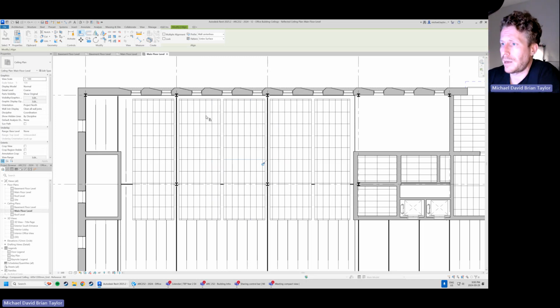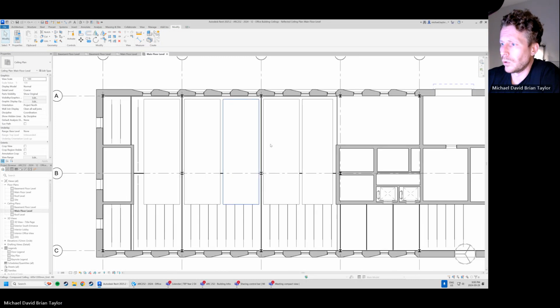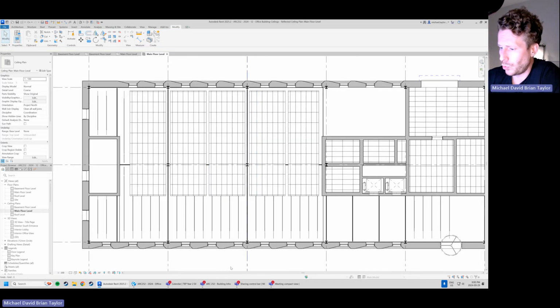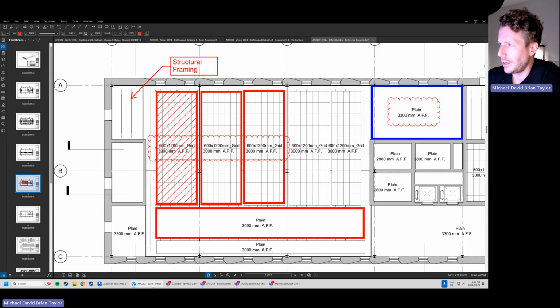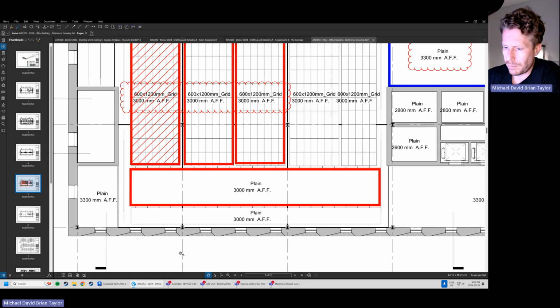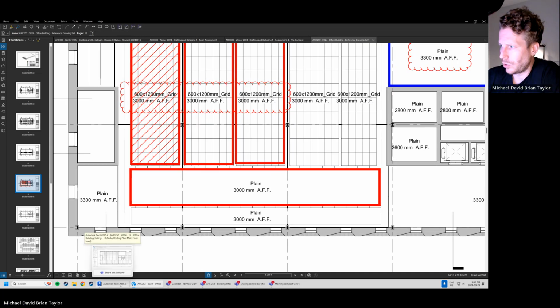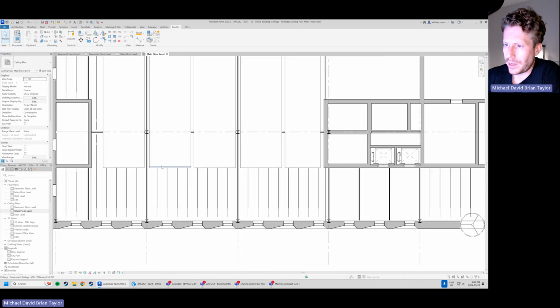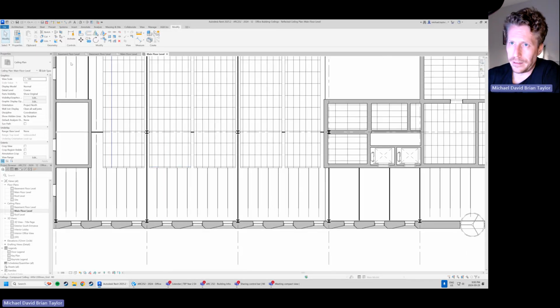If I just, again, double tap escape, we're getting pretty close to what our best in town example looks like. We've got a couple ceilings here. There are, again, just these plain ceilings at the base here. And why don't we just go ahead and make those elements. Back into Revit, we just got to make something like these ceilings. So we'll come back up to architecture. Did I make them the same elevation? Let's just double check that. So yep, they're all 3000.